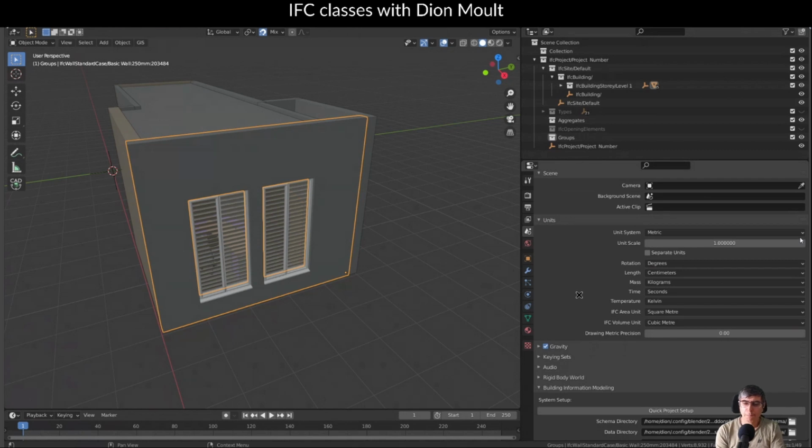So just be aware that there are some attributes in IFC that are not so simple to store because they're a bit more complicated than just a piece of text. And so you might need to search. If somebody says, hey, can you please set the unit attribute on your project correctly, what they actually mean is you'll have to search for somewhere in your project, in your BIM program settings. But effectively, what you're doing is storing an attribute.